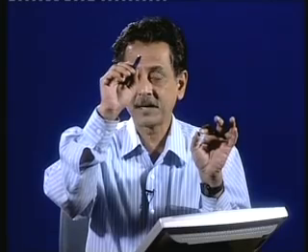So, this will handle the MAC part of it, we are not going into the details of this, but anyway this will go to the hub, and from the hub again it will go to the satellite and then go to the point B, say A was the sender and B was the receiver. So, from A to B, it goes in 2 hops. So, the space delay is doubled, because we are going in 2 hops. Sometimes with the help of a satellite modem kind of thing, you can go in 1 hop. Those channels are more costly, otherwise the usual one is 2 hops.